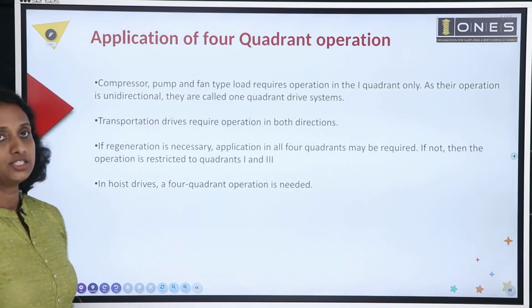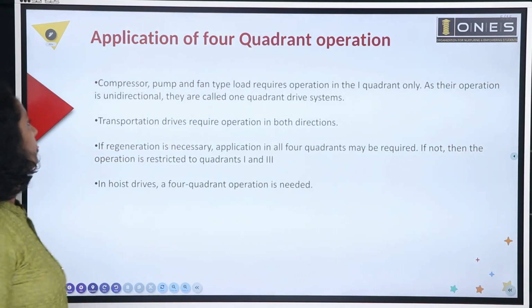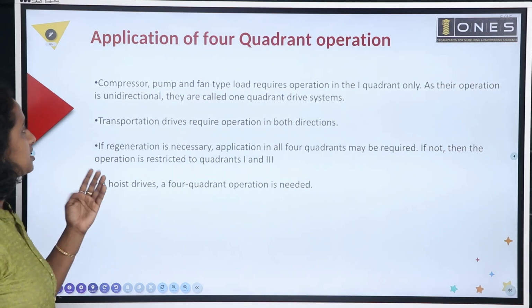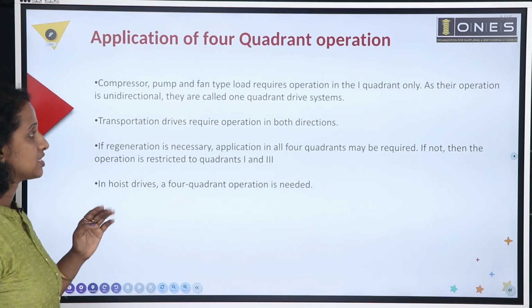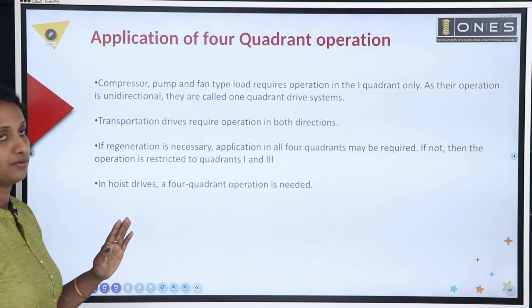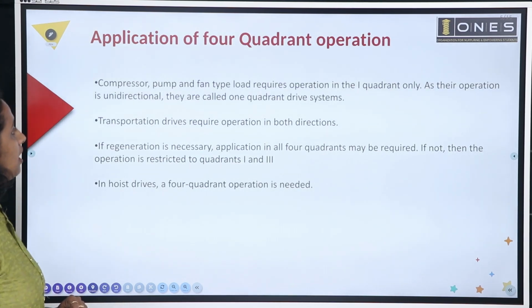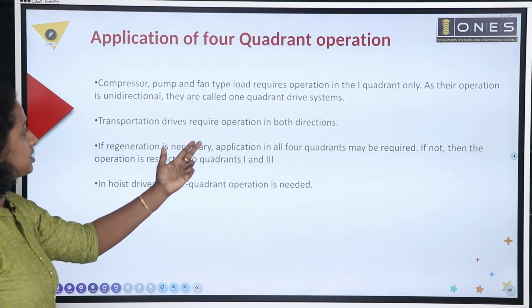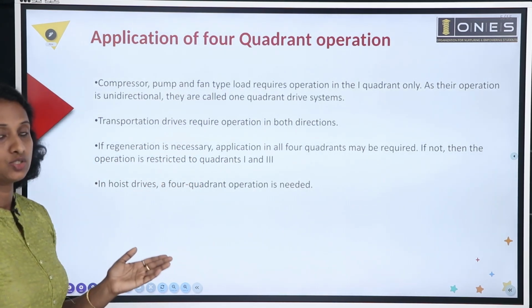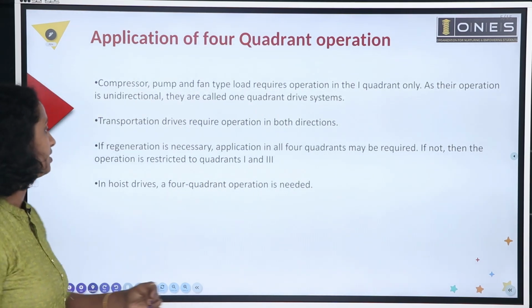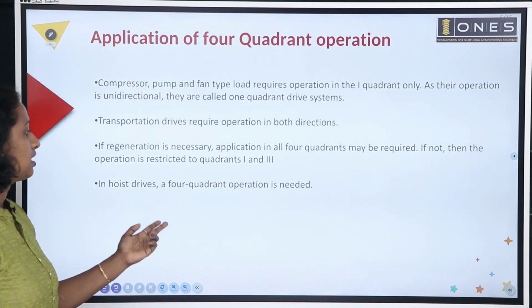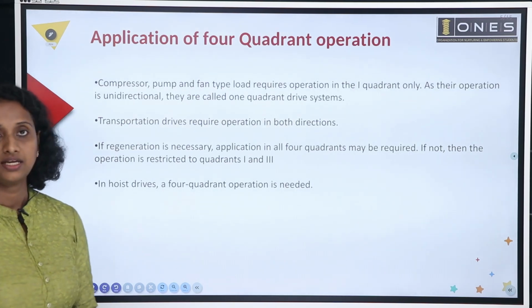Now the applications of 4 quadrant operation: compressors, pumps and fan type loads, where first quadrant operation only is needed. Transportation drives require operation in both directions, so only 2 quadrants of operation are needed, that is first and third quadrant. In hoist drives, 4 quadrant operation is needed.